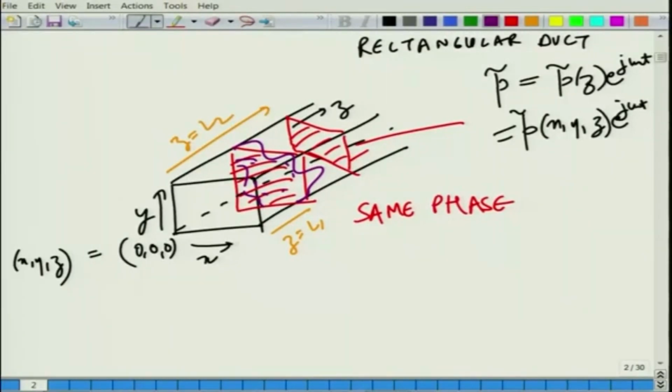So, the purpose of today's lecture is to present to you the set of consolidated lectures 3 to 5, in which I would initially begin with a derivation of the acoustic wave equation in a Cartesian coordinate system, but involving the other two coordinates x and y, and z of course is there. So, that would be the 3-dimensional wave equation, but in a stationary medium, and that will be valid for rectangular ducts once we implement the appropriate boundary condition, whether it is a rigid wall condition or open end condition.